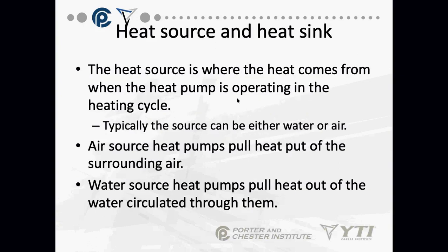Heat pump source is where the heat comes from when the heat pump is in the heating cycle. Traditionally, the source can be the air outside, or it can even be water. We have something called an air-to-air heat pump that takes the outside air, absorbs the heat from the air, and pumps it off into the inside air. We also have water-to-air heat pumps, otherwise known as geothermal units. We absorb heat out of warm or warmer water, and we move it into the inside air.